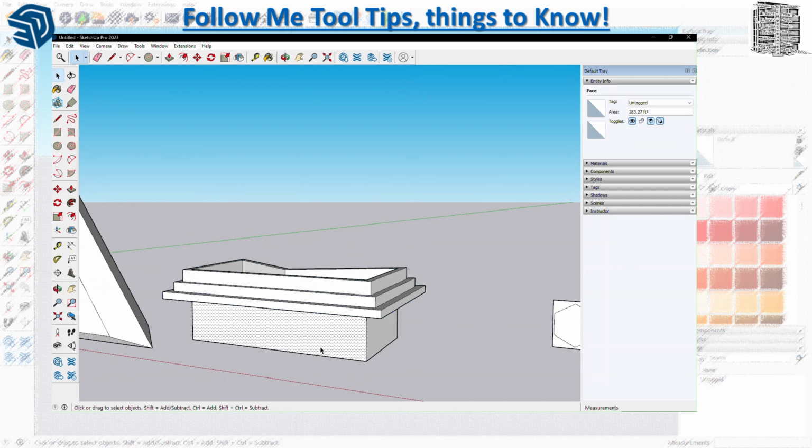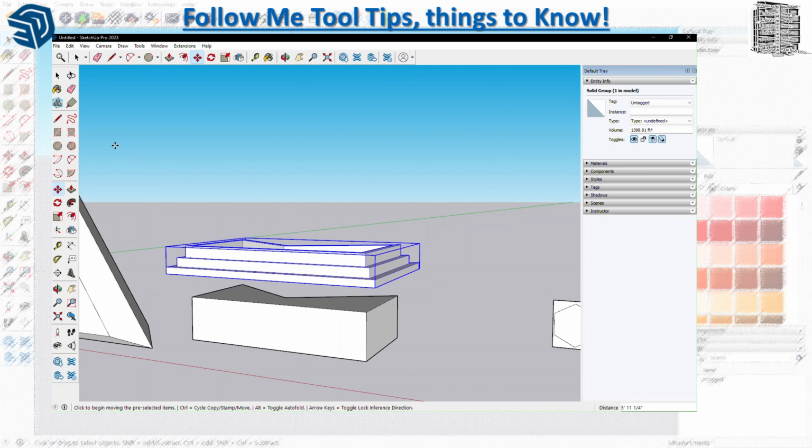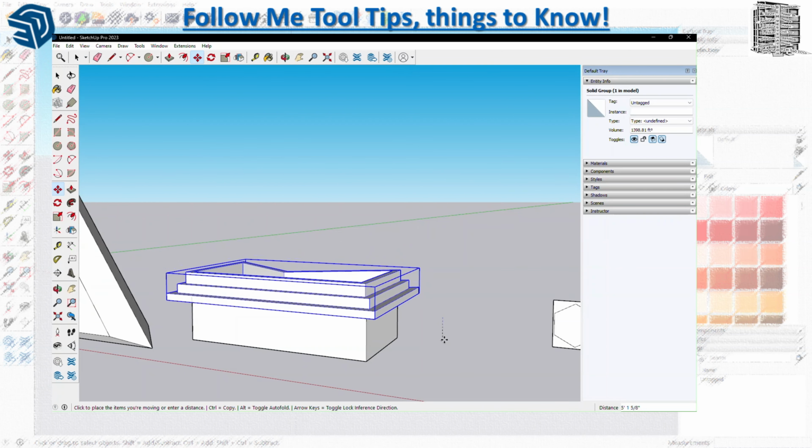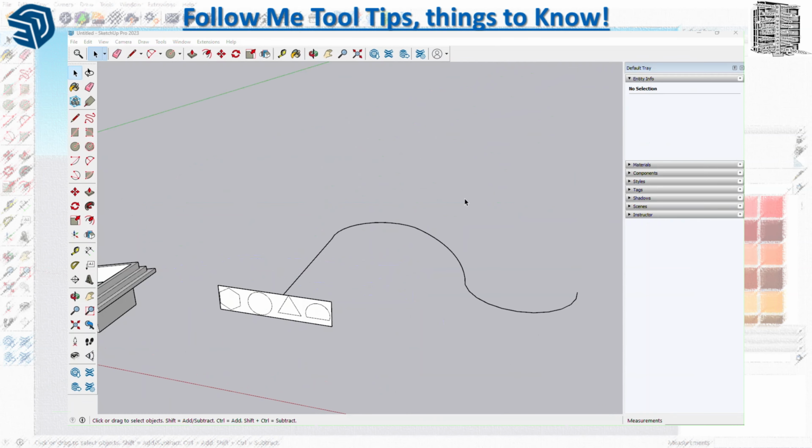And you can see the shape below, it's not grouped. If it's grouped, it's not going to work, so you have to explode one of the objects and keep the other one as a group so you can adjust later. So simply you can leave the other one, group the bottom, put it back on, and you're good to go.